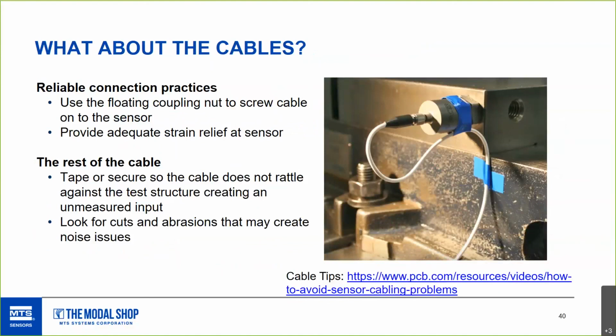There's a lot of cable options. Consider the bend radius. Make sure that you're not measuring cable width as part of what you're testing. Usually modal shouldn't see so much displacement, but consider using things like extension cables, both for your single axis or triax. If you had something wet, we have IP68 rated cables for operation if it's dusty or humid.